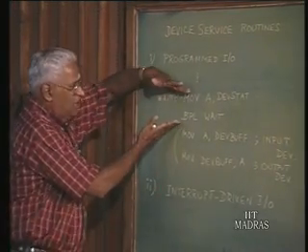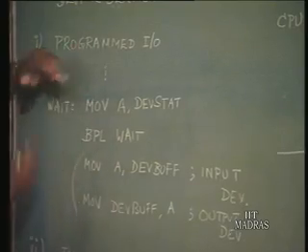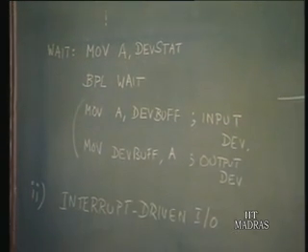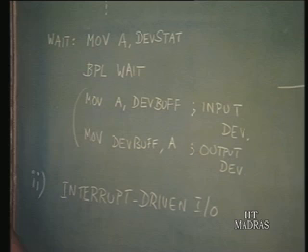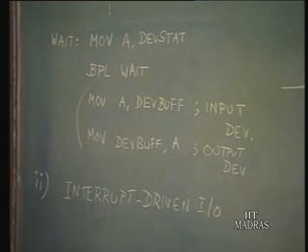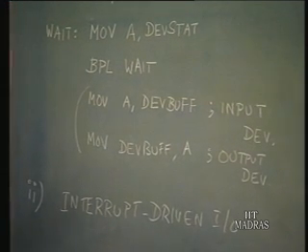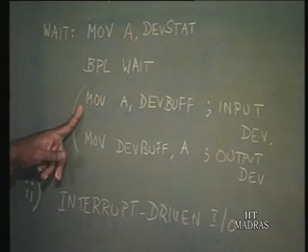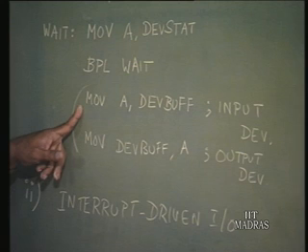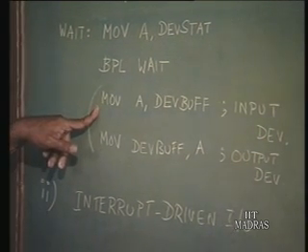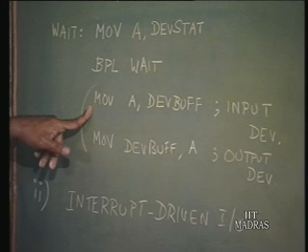That is, the device status checking is not there in this case, only because the device is ready it has interrupted the processor. Good. If that is so, what is there in the program? The interrupt service routine will essentially consist of the data transfer part and anything else associated with it, as I said earlier, counting of how many bytes and so on and so forth.